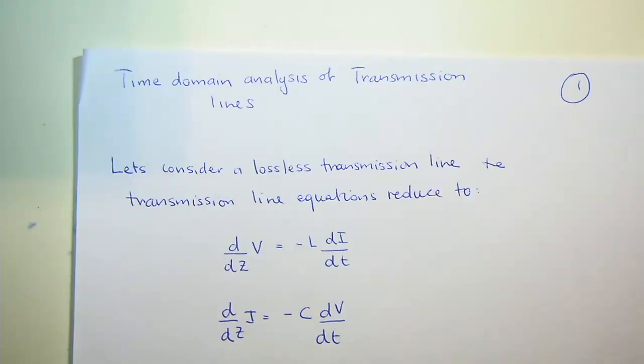So all of a sudden you switch this line from voltage 0 to voltage 1, and all of a sudden you've got something at the end of that transmission line that's going to transition from a particular logic state to another. So let's assume that it's a latch rather than a flip-flop, which is actually clocking. It's only going to measure the signal at a predefined moment in time. So essentially what's happening is that latch is going to see a time-varying voltage.